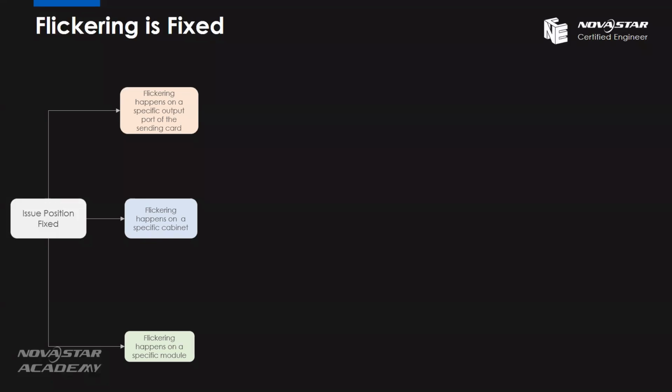First, if it happens on specific output ports of the sending card, what do we have to do? It's very easy. We can just exchange the Ethernet cable to another output port. For example, now you have a screen using 4 output ports, but the port 1 loading area is flickering.